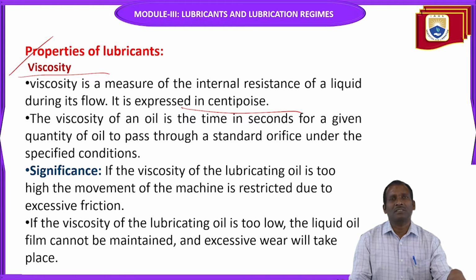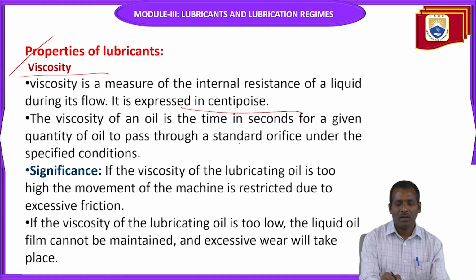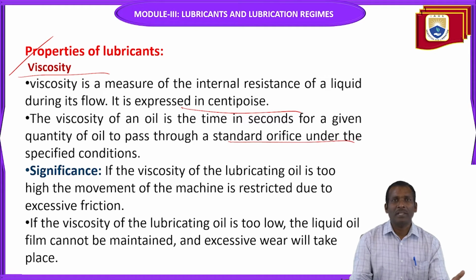How thick the oil is, and how thick the lubrication film is, it represents the viscosity. The viscosity of an oil is the time in seconds for a given quantity of oil to pass through a standard orifice under specified conditions. So by using a standard orifice, you can measure and find the viscosity.